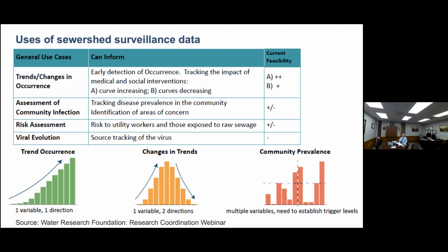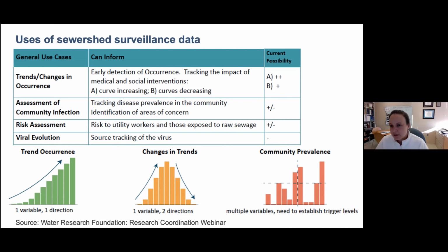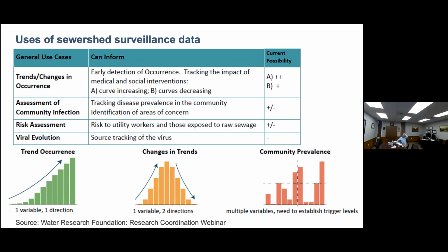So potentially it could be used for a tracer. It wouldn't be the tracer I would use because it does decay. I like chemical tracers better for sure. But in terms of what's much more common, it's for us to look at E. coli or norovirus or adenovirus or some of the enteric viruses. Those have been used to show evidence of septic contamination of groundwater, certainly.